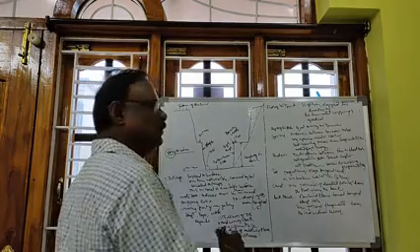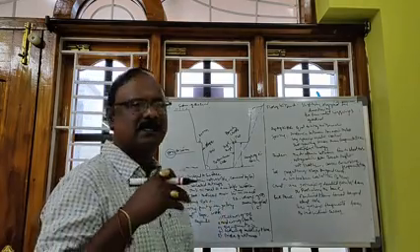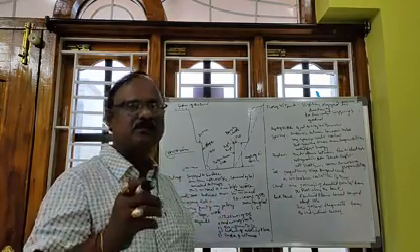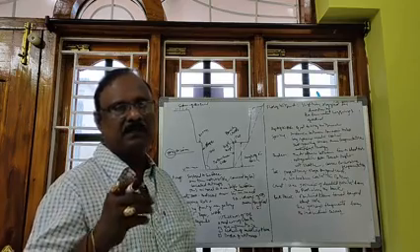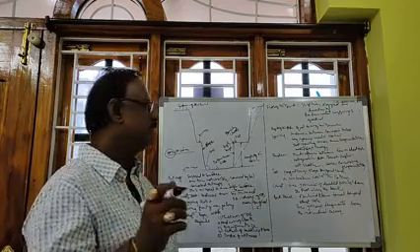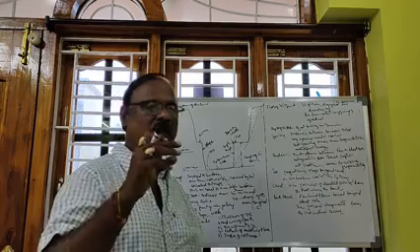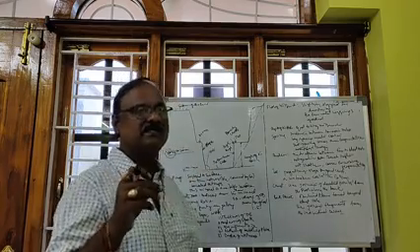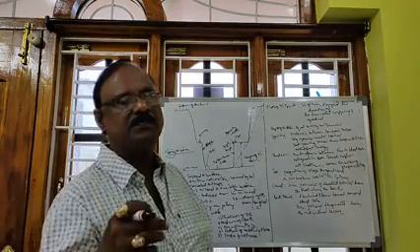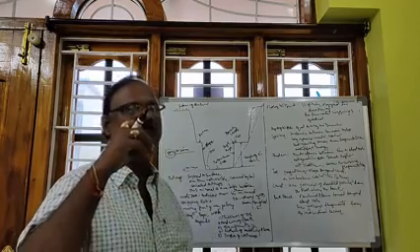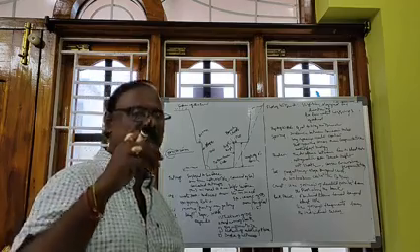The box cut is made at the beginning, and from that onwards, the OB is converted into different benches, 5 benches. So the bench is nothing but similar to a step. The step has the width of the bench, the height of the bench, and the slope of the bench. What are the different features the step has? The same features and characteristics the bench has.